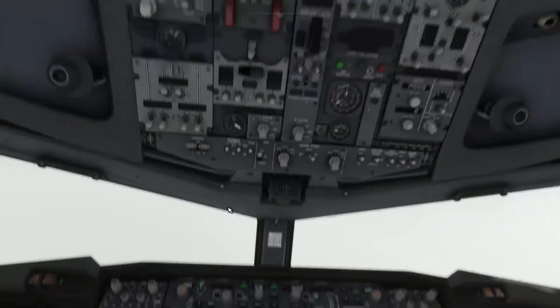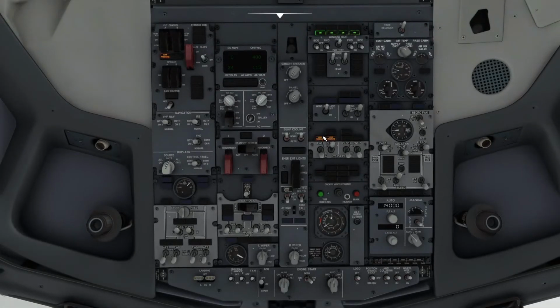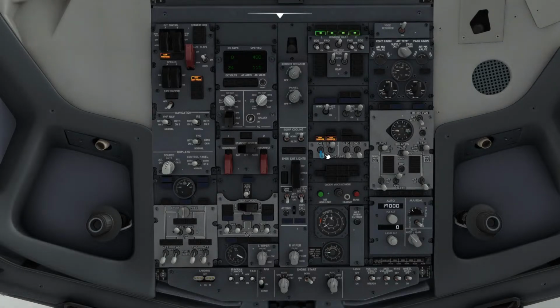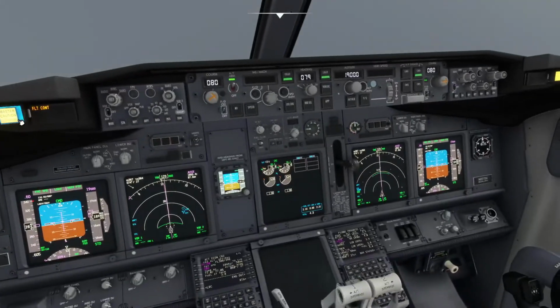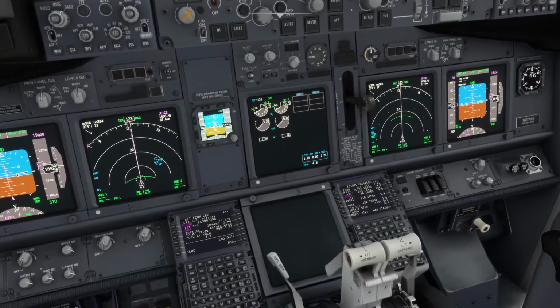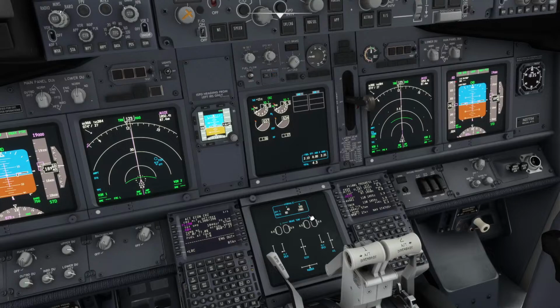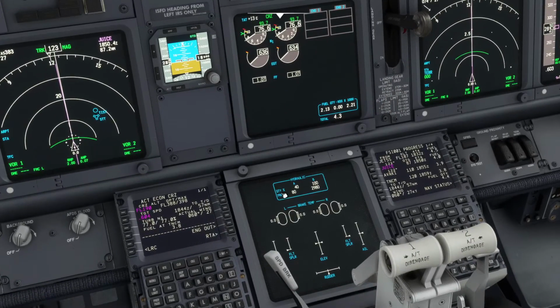And let's look at our overhead panel. So now we lost both pumps on the system A. We have the low pressure for flight control A and the fuel differential pressure as expected. We can clear this again, and we can open here the system to see that the quantity in percent is around 40% and the pressure is around 80.